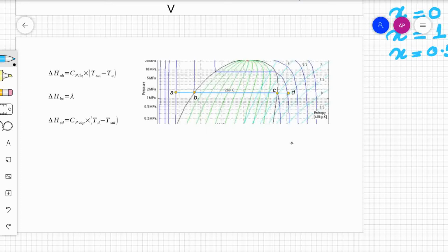Reminded to you once again, and as is obvious from this diagram, when it goes from B to C, the pressure is constant and so is the temperature. It is because when it is going from B to C, it is boiling. Boiling for pure fluids is a constant pressure and constant temperature phenomenon. By this, what I mean is, if you hold the pressure constant, there is only one unique boiling point that the fluid is going to have.